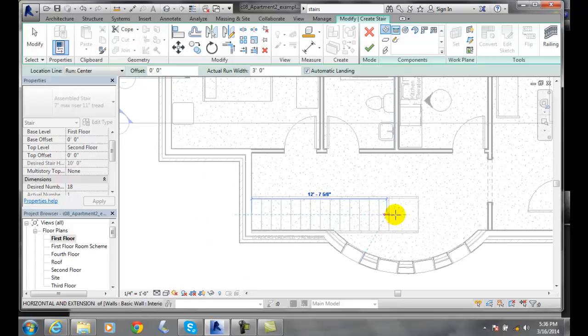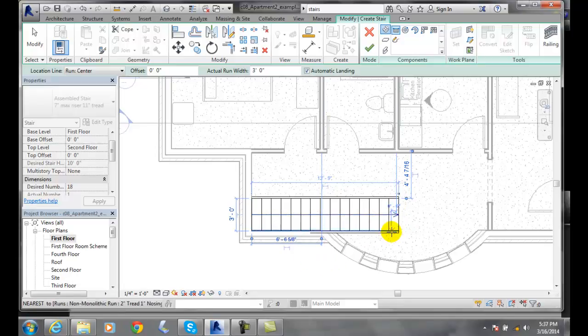I can go all the way out to here as a maximum. You can see it won't build any longer. It's the longest run of stairs I can make. I can make them shorter a little bit, and you can see once we get down, it's not going to be long enough. So we stretch out to as many stairs as we can put into the area, and I'm going to line up right there with that wall. That looks like a good location. I'm going to click.